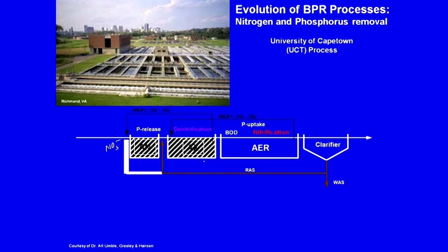And then obviously you need to have an internal circulation. Why is that? If it is just straight flow, there are not going to be any microbes in the anaerobic tank, let us see. Obviously you need to have recirculation here. So, here you are going to have anoxic conditions, where nitrate is being degraded to N2, right, and you have a system that has relatively less nitrates at the end of the system. So, if I recycle from here to here, the nitrate concentration will be relatively less, and anyway influent wastewater, I know that oxygen concentration will be relatively less.